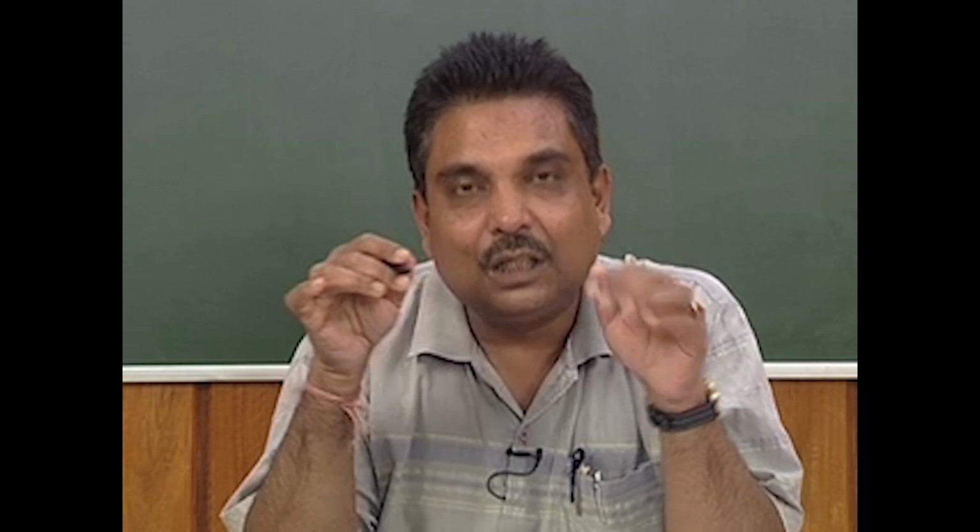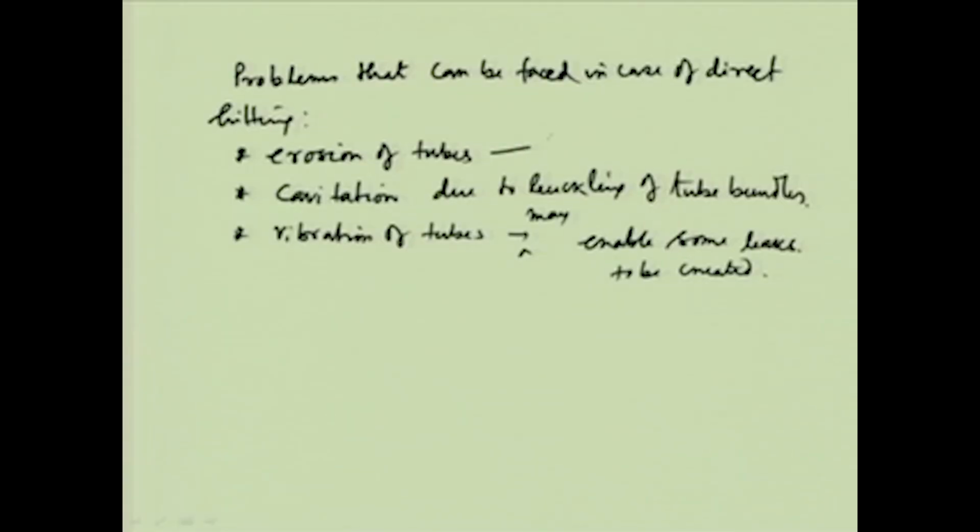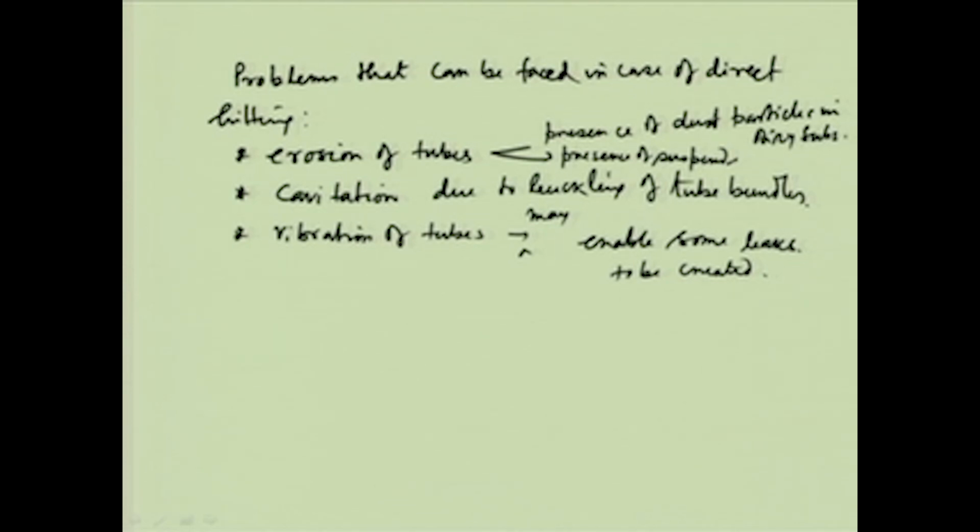This erosion will be more if it takes place due to the presence of dust particles in an airy substance, or the presence of suspended solids in liquid.